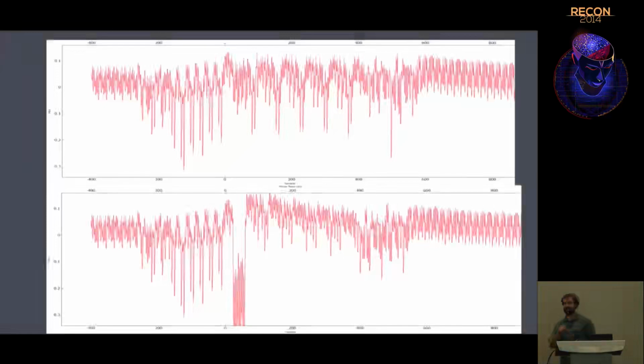In that case, the glitch trigger, for that demo, is set up so that the microcontroller sets an I/O line high when it does it. You can do the same demo, and this is what I have here, where the glitch trigger is based on the power signature itself.